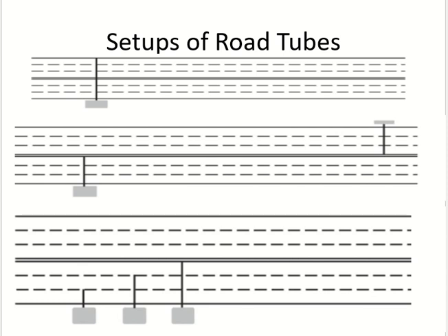For the second lane, I cannot make it from this edge to this edge, because then where will I put the sensor? So the tube has to be from the side to the second lane. It will give me data for 2 lanes, so I will have to do some deduction from the first lane to get it for the second lane only.